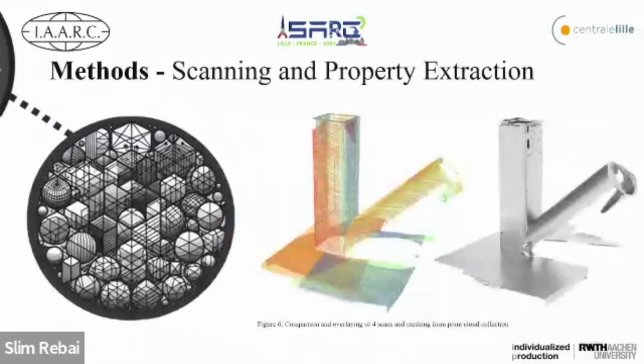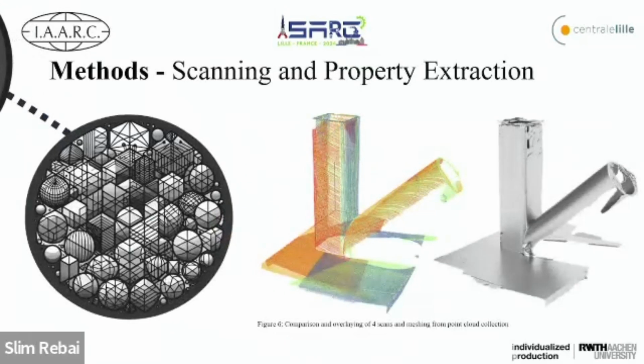And at the end, for example, talking about line scanners, they have laser profilers. They have high precision, but lose some of the coverage. As you can see, for this example, a steel beam edge connection, we had to scan 4 times, and then you can see that they are more or less registered to each other, and at the end, we just apply the meshing algorithm to see if it makes sense.